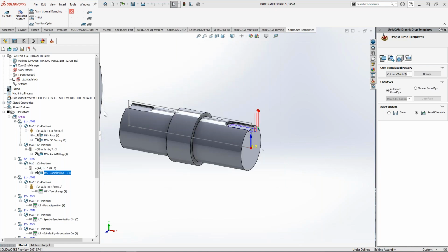It came to support very often, especially for the Mill-Turn projects and also Swiss type, that the conversion was done smoothly, everything is nice, but then after generation of the G-code and comparing it with the project in the earlier version, there is an indication that the plane was actually different. Okay, so for some reason the plane that was G17 is now G19. After investigating, we realized that the get tool direction in station is giving us a wrong value.